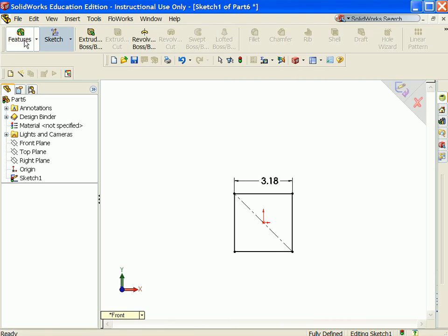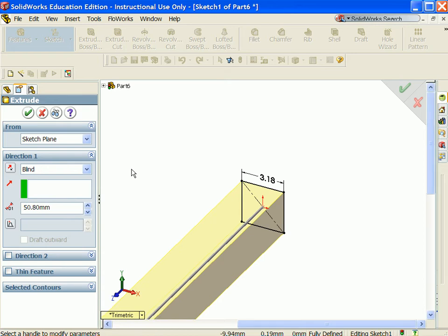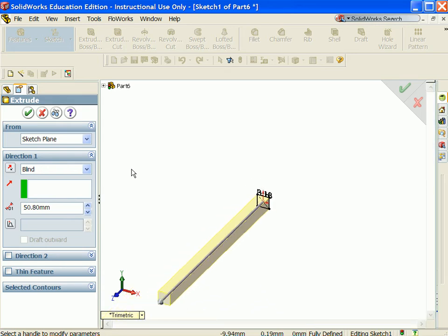Robot design tip number 5. I want to build symmetry into the feature. I select on Extrude Boss Base. I'm working in millimeters, but I know Vect ships a 2-inch shaft. I enter in 2IN and SOLIDWORKS will convert the value into millimeters.